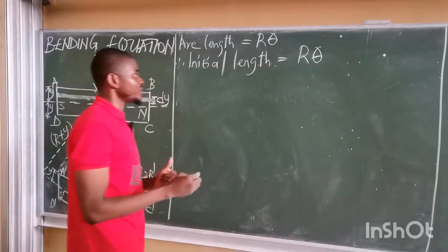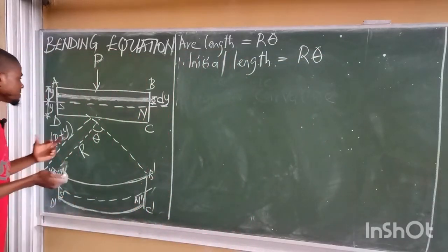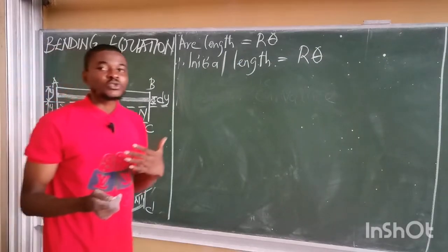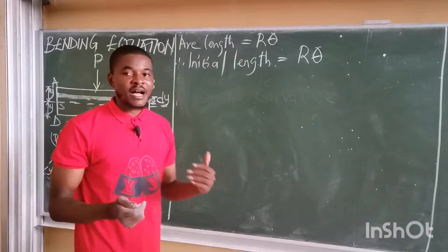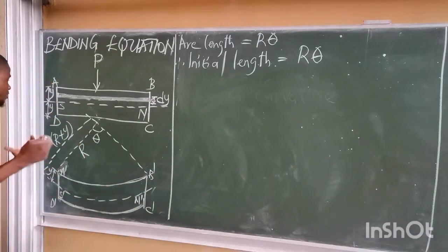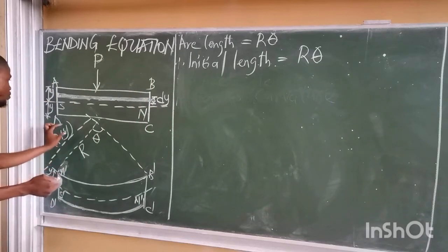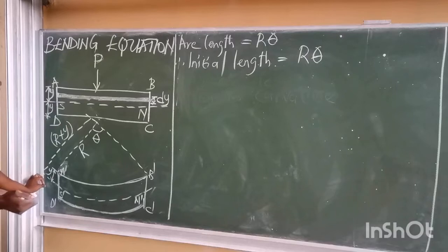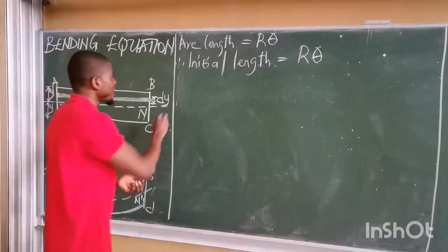So we have this. Now the final bend is the bend about the neutral axis. That is where bending is maximum. So that length is about the neutral axis. And we said from the center to the neutral axis, the radius is simply the radius of curvature plus what? Y. That gives a total distance from the center to the neutral axis. Therefore, we can obtain the final length.